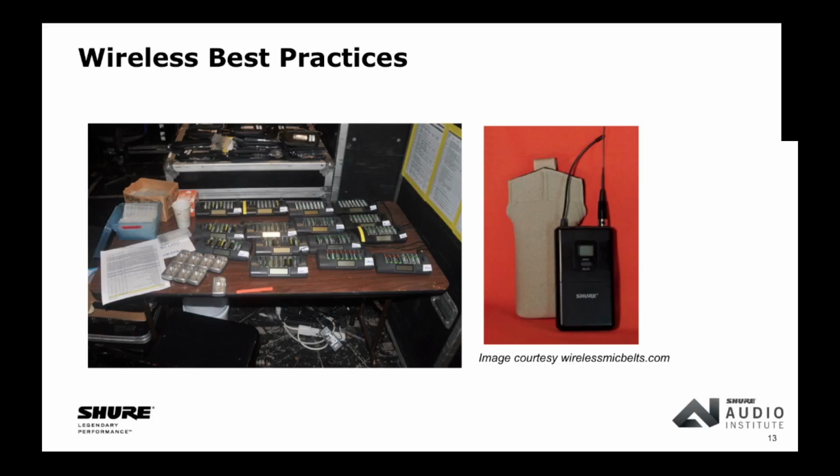There are a few options on the market that claim to be hermetically sealed and theoretically would be okay with that. But there's always a point of entry where the sweat can become a problem. Where the mic connects to the body pack. Exactly. That's one of the biggest ones right there. The technique we've used for the longest, in the old school Broadway world, was to use unlubricated condoms. You put the condom over the mic pack. It's an expensive solution. They break. They're hard to put on.